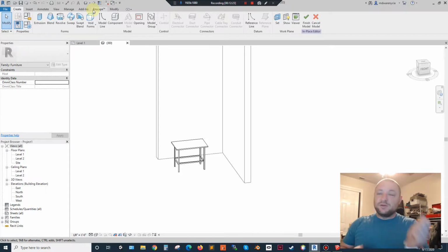You create one door, you copy and paste it a bunch of places, and you can create a series of cabinets. So think of small ways to segment things out, break them apart, and then combine them back together in order to create something to represent what you're trying to model that Revit may not have an exact copy of.